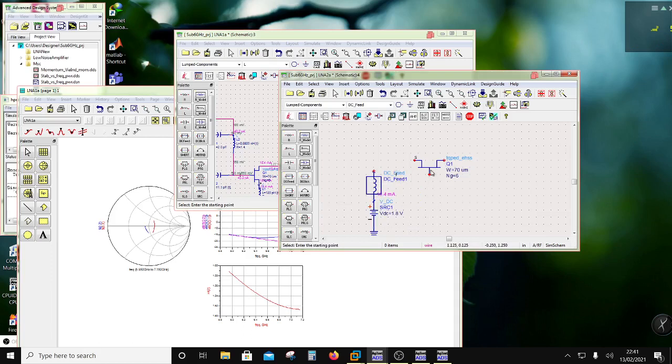And then I have to have a, so basically, okay, so I need to put a feed here, right? Isn't it? Yeah, because the current is supposed to flow all into this supply, right? So I need a DC block on the other side. So DC block, lump component, DC block. So I'm going to put the DC block on the other side, right?